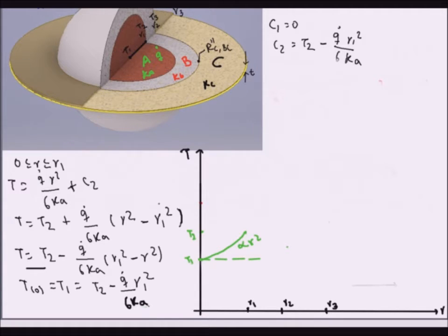to know how the temperature profile looks in material B, even though we didn't solve for the temperature profile, we can show how the sketch would look, or the shape, based on the endpoints. So we know that the first point was T2, and the next point is T3, which we don't necessarily know, but we know that it must be higher than T2.